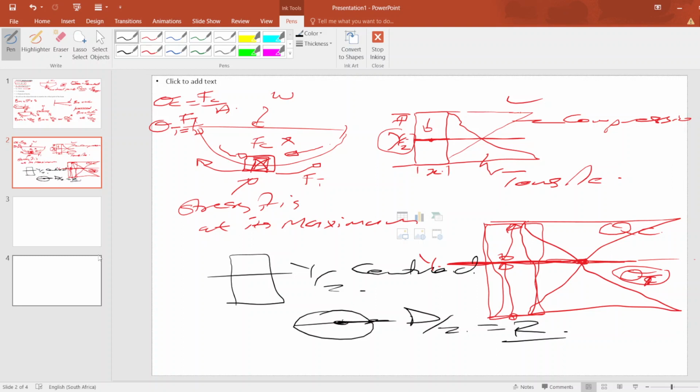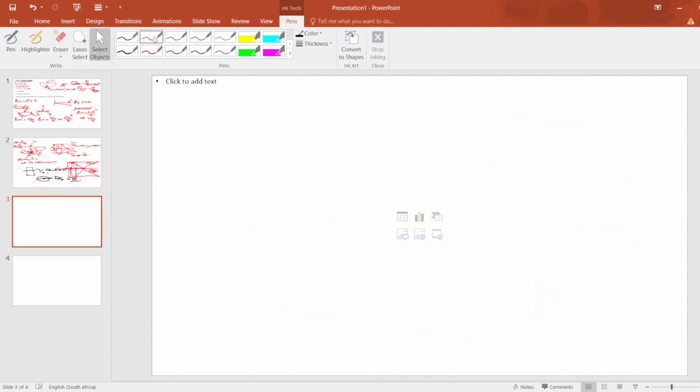But if you are given a compounded beam, like this one here, let's look at the T beam. This is a compounded beam. If it is a compounded beam, then you will have to use area moment in calculating the centroid. You then have to partition your beam based on familiar shapes whose area and center you can calculate.